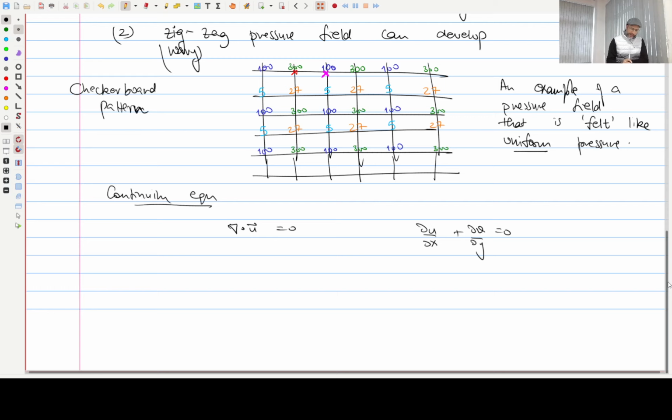So if you solve it using finite volume, then this is integrated over a control volume, and then this becomes u on the face dotted with the delta gamma vector on the face, summed over all the four faces, right? That's what finite volume will give us. We apply the Gauss divergence theorem first, convert this volume integral to an area integral, and then convert that area integral to a sum over four faces. I've just done it in one step.